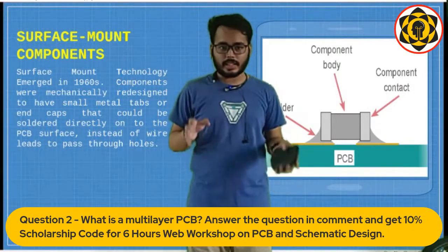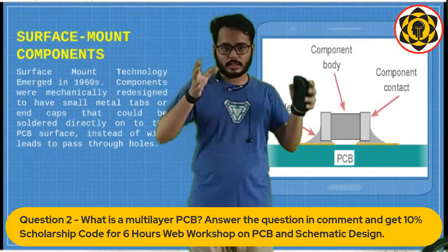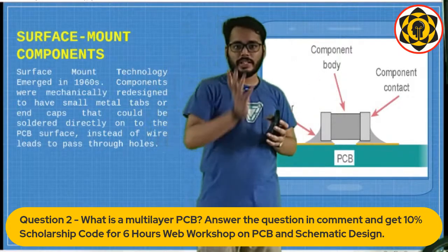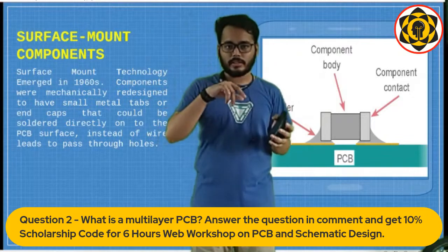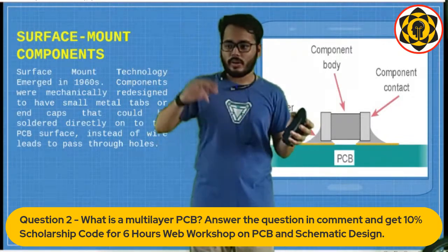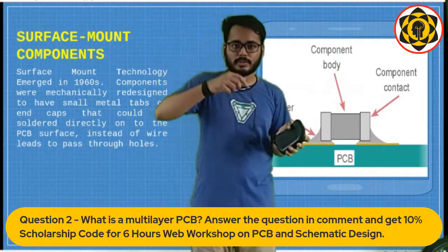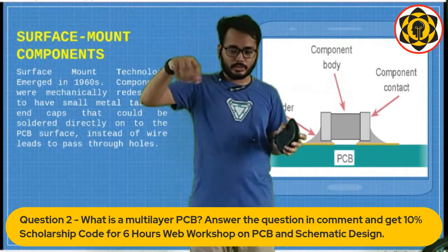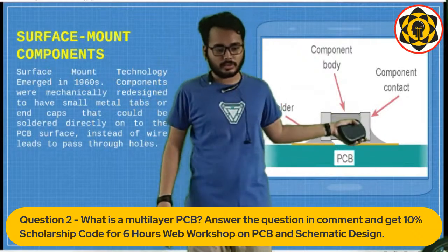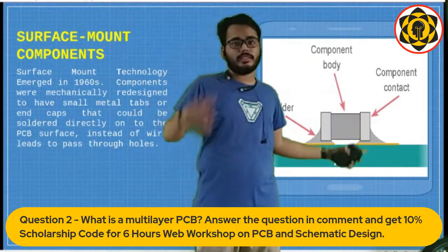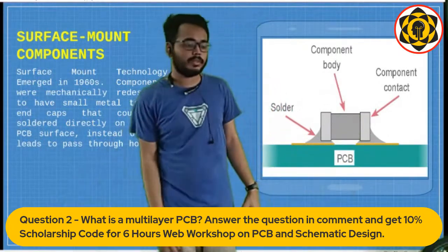In that case, the circuit that you are making is either placed on a very hot surface to induce heat on the whole circuit so that the pad gets heated automatically, or you can use a hot air gun. As the name suggests, hot air comes out of it. You can adjust the temperature and blow that hot air over this soldering pad. It will get heated up, and then the solder will melt and seal the bond.